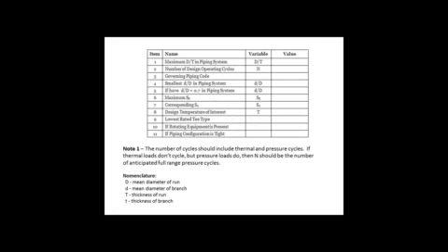Now the question is, are you going to send us a piping system to analyze for you where the D over T ratio is 17? Probably shouldn't because it's not going to help much. Are you going to send us a system where the number of cycles is 200? Probably shouldn't because even if the SIFs are higher, it's not going to really affect the practical solutions in the piping analysis. So if we go to the next slide, here's the collection of the critical data.